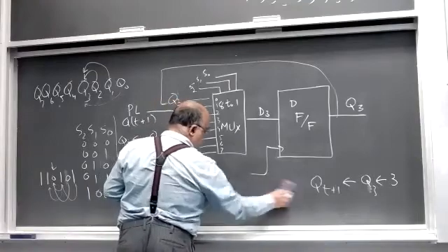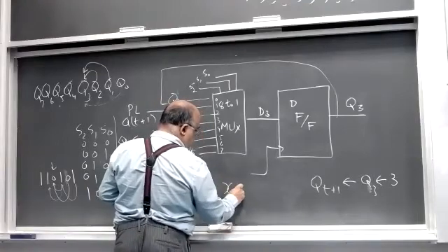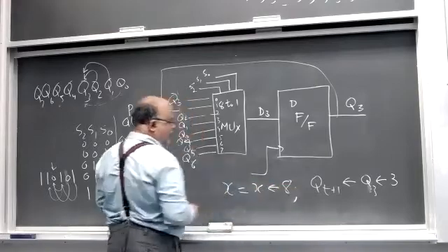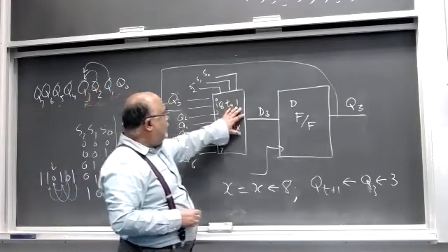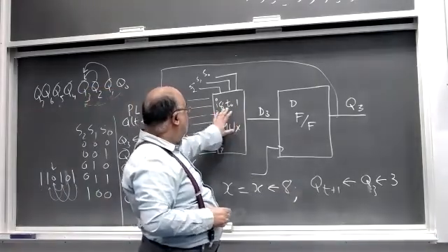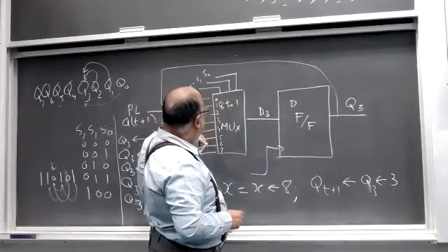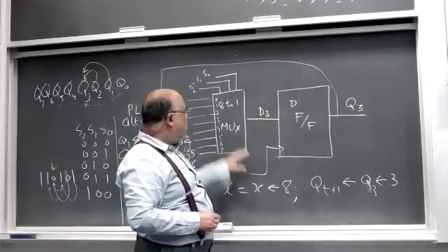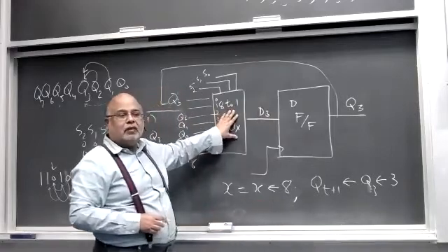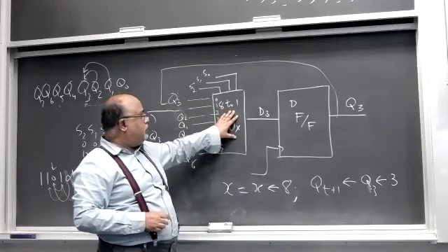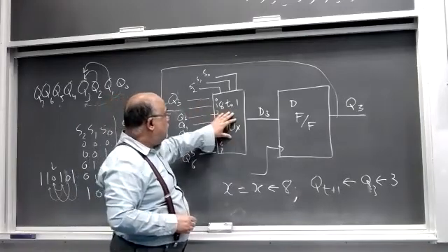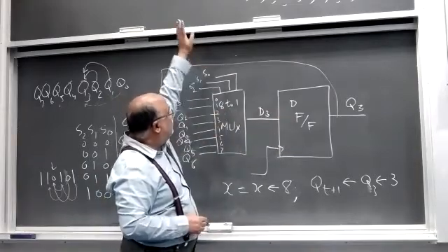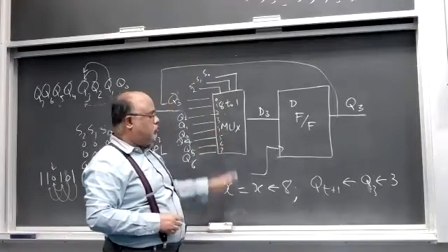या अगर मैं Q में कहता हूँ ये वाली चीज कि x equal to x shifted left 8 times, इसका मतलब कि उसमें हर एक के जो है ना डी फ्लिप फ्लॉप, उसके अंदर 8 ऊपर के नेबर भी हैं, 8 नीचे के नेबर भी हैं. इतना बड़ा यहाँ पर मल्टीप्लेक्सर है. और 16 बिट शिफ्टिंग के लिए इतना बड़ा मल्टीप्लेक्सर है हर एक इनपुट पे कि you can select 16 में से इधर की 16 में से कोई एक सिलेक्ट कर लें या इधर की 16 में से कोई एक सिलेक्ट कर लें.